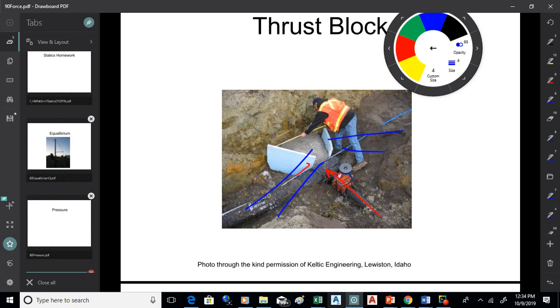Now what's the problem with that 10 years from now? What do you got to do if you go? Yeah, exactly. And again, that's another one of them things where I prefer talking about that in the classroom than I do to actually be out there doing it. I wouldn't want to have to get that thrust block off of that valve if I need to replace that valve. That wouldn't be much fun.